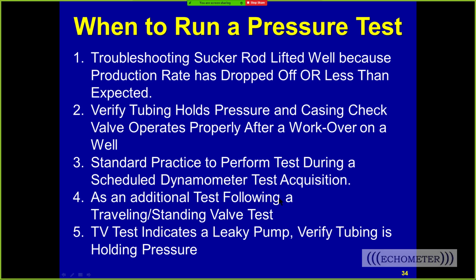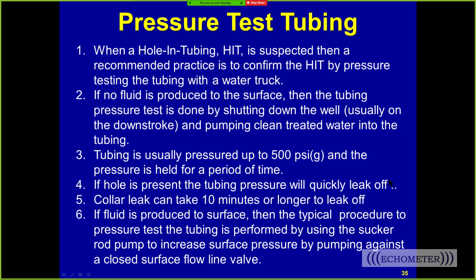You can do this as part of a valve test if you want. And if you see a leaky pump or a leaky traveling valve, then you can also see if the tubing will hold pressure, and is that a pump that's leaking, or is that just a hole in the tubing. So there are different types of tests that you can do here. A lot of times if you have a problem about a hole in the tubing, you might want to pressure test the tubing. And that's assuming that you're still producing some liquid to the surface.